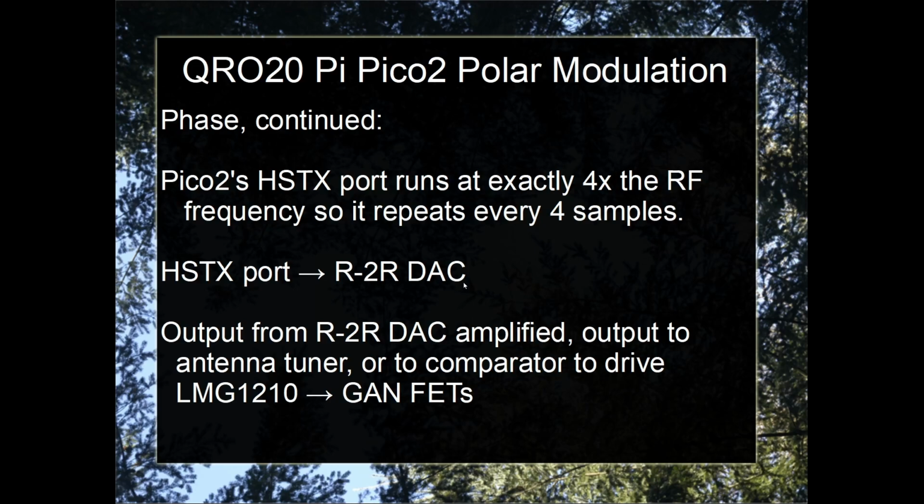It's not the most linear way to do a digital to analog conversion, but for 8 bits, it's going to be just fine. And it turns out that 8 bits is still plenty of resolution to get typically 48 to 50 dB, especially if you use 1% resistors. And worst comes to worst, you can always do some linearization in software.